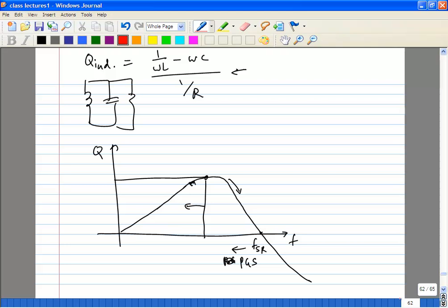At that point, you need to make a decision on whether you want to match the impedances or whether you want to work with lumped elements. For example, I think we discussed this in the first class: inside the chip, you try not to match. Let's say if you have an LNA, you want to drive a different circuit. You don't necessarily have to match the output to 50 ohms.